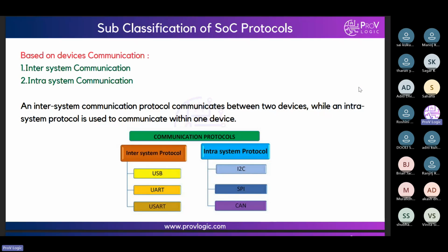Internal clock issues or internal node connection issues can be there. Even in pre-silicon verification we can't say 100%, even with 100% coverage. At any point of time we may get errors whenever we dump into the hardware. That's why post-silicon verification is a must.